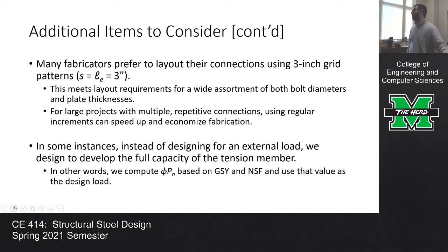And finally, I do want to talk about this idea of developing the full capacity. We're not going to use this in our example today, but I want to explain. This actually relates to step 1 in our process. In our design, what we do is we take the load on the connection and we divide it by the capacity of a single bolt in order to get the number of bolts.